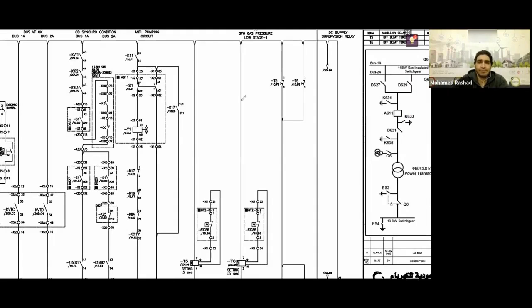This is its diagram. You have something like this, let's say it like this. So now you have the timer. As soon as this signal reaches it, the timer immediately changes the states of its contacts. Normally open becomes closed and closed becomes open. As soon as this signal is removed, meaning if this contact opens, from that moment, it starts counting the time you set for it. Then it returns the states of its contacts to their natural state.